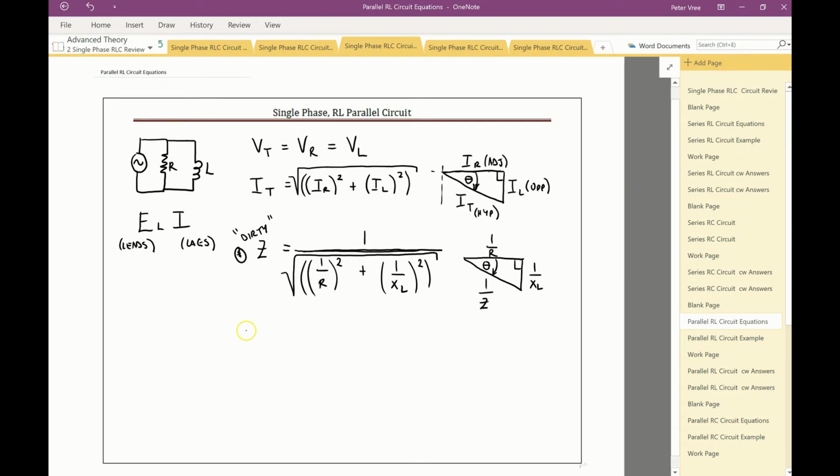Okay, the VA equation for this: there is no difference in the power equation for series and parallel circuits, so it's the exact same as the previous circuit. If you haven't watched that video yet, we have a number of different terms here. VA is your volt amps, watts is your wattage or your true power, and VARs is your volt amps reactive, so that's potential energy held in the magnetic field. Again, it's adjacent squared plus opposite squared. We take the square root and we find the total for the circuit. So the VA is a combination of the wattage, heat and light, and the VARs, meaning the potential energy held in the magnetic fields.